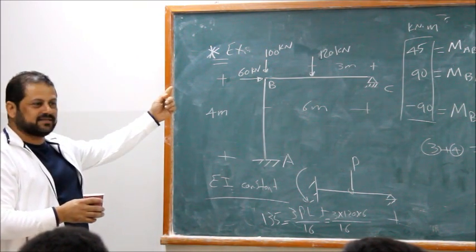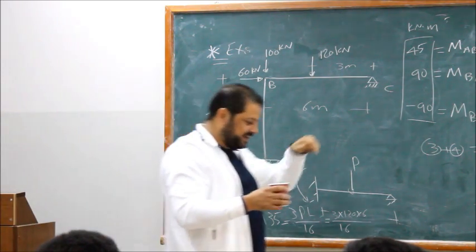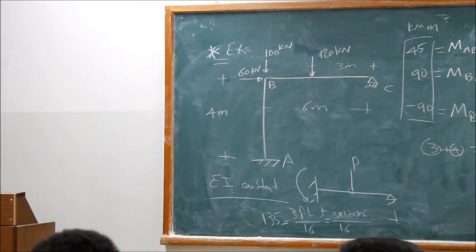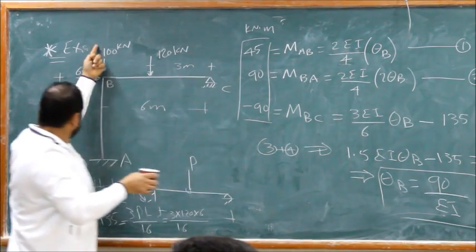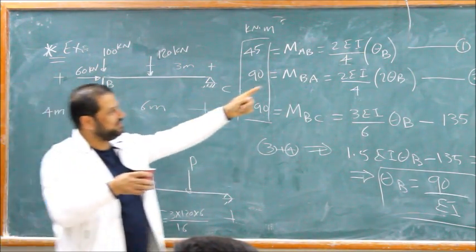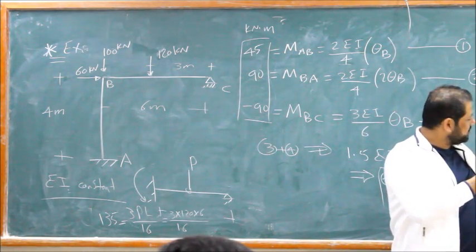When you see something like this, the theory is easy, guys, easy. If you are standing directly and there is a column under your foot, all of your load goes directly there. The full 100 went directly as an axial in the column. We added 100 to 75 and it became 175.